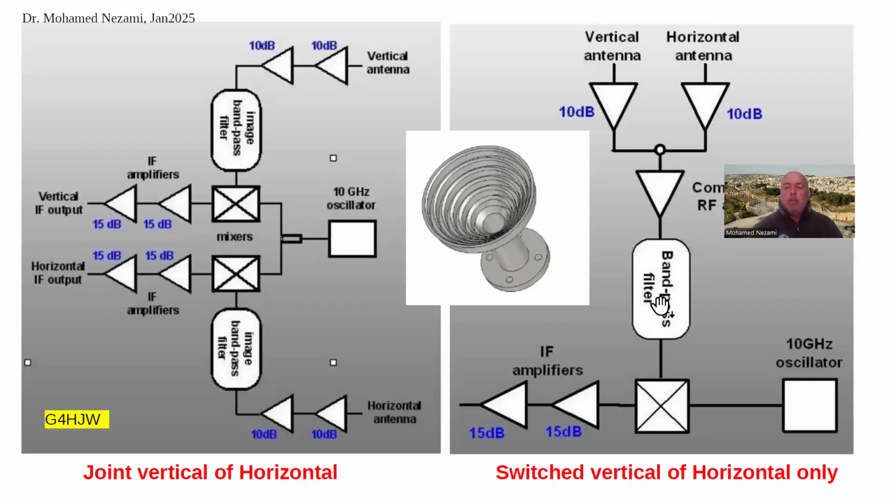So the LNBs that we have covered in my series, if you refer back to the other videos, I have taken from this source here, just a block diagram showing you how you go with the vertical and horizontal. Some of these LNBs will switch the power on either one of these. You get a signal from the indoor modem to the LNB to tell it to go either vertical or horizontal. And then it goes in, and of course, we down convert, and there goes the IF. So you switch between vertical and horizontal.